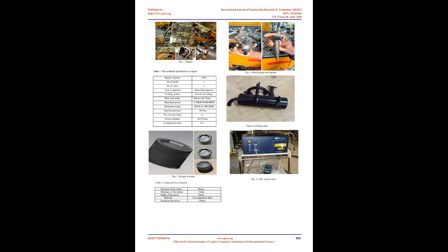The diesel combustion equation is explained as 4C12H23 + 71O2 → 48CO2 + 46H2O. This is for the complete combustion of diesel, which does not happen in real-life practical conditions. Other products can include CO and unburned fuel. When the reaction is not complete combustion, this results in less energy.